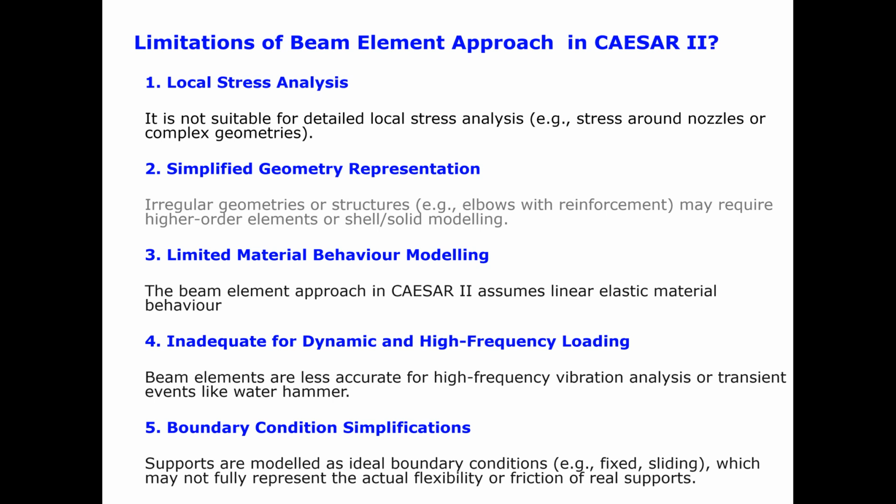Fourth one is inadequate for dynamic and higher frequency loading. The dynamic analysis limitations: beam elements are less accurate for high frequency vibration analysis or transient events like water hammer, damping and resonance. Similarly, the simplified damping model may not accurately represent the system's response to dynamic loads.